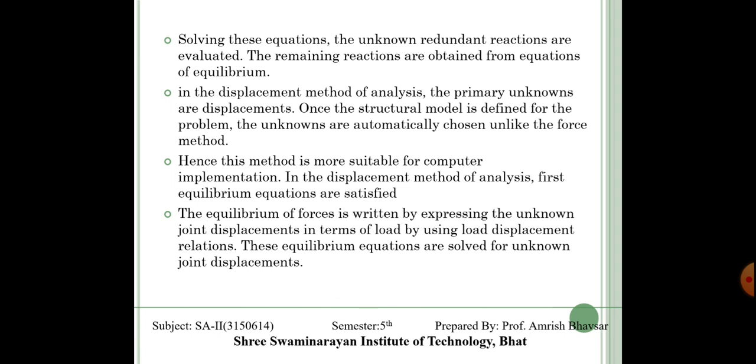In the displacement method of analysis, first the equilibrium equations are satisfied. The equilibrium of forces is written by expressing the unknown joint displacements in terms of load by using the load displacement relation. These equilibrium equations are solved for unknown joint displacements.